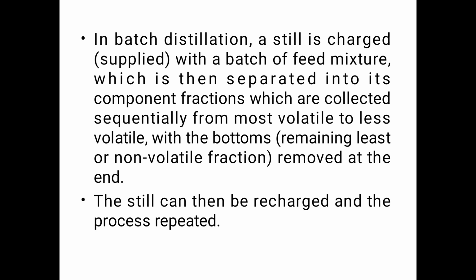The still can be recharged and processed repeatedly. The feed will be recharged, the process will be stopped, and the feed will be recharged again, then the process will start. But continuous is a different process. The feed will be fed continuously to the process and product withdrawn continuously. In the laboratory process, once the feed is fed and product is collected, after that it is again recharged with feed to the distillation column.